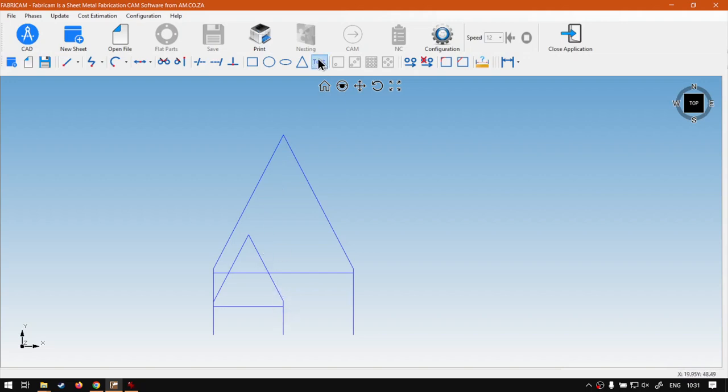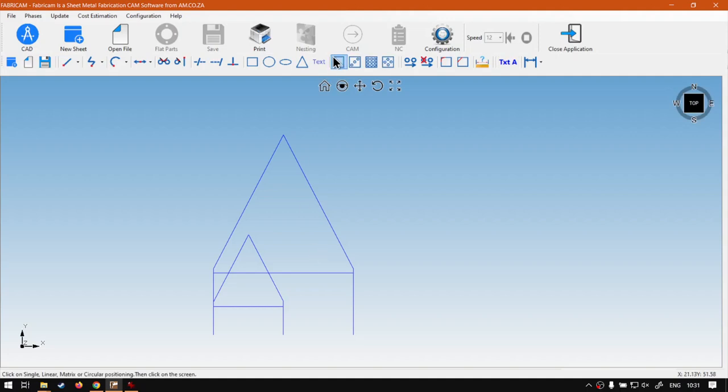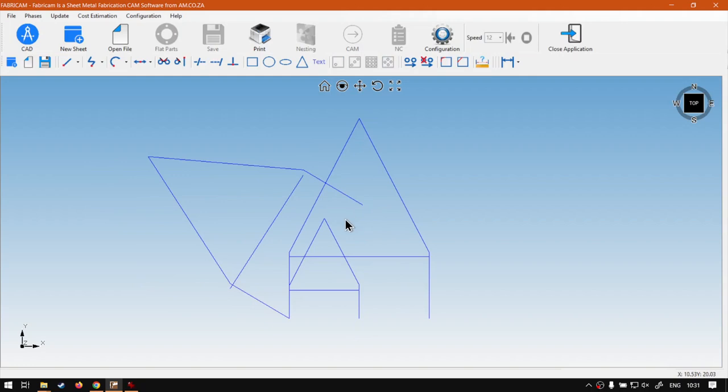Now when it comes to the actual alignment, let's grab another capital A and make this also 40. Then we've got the degrees amount we can set. At the moment it is 0, so let's go about 45, say OK, and position it in. You will see it gives us a nice rotation there, keeping in mind, once again, the origin point is going to be the bottom left of your text.